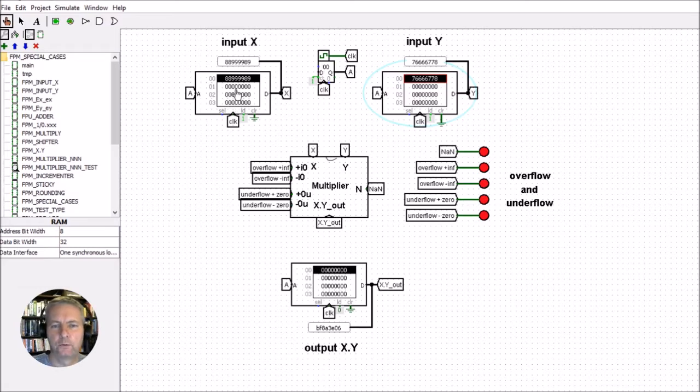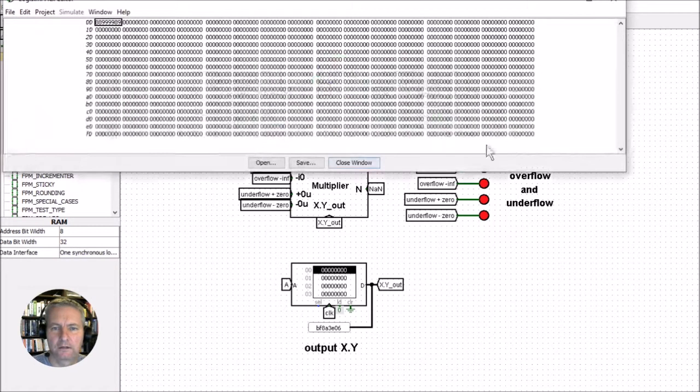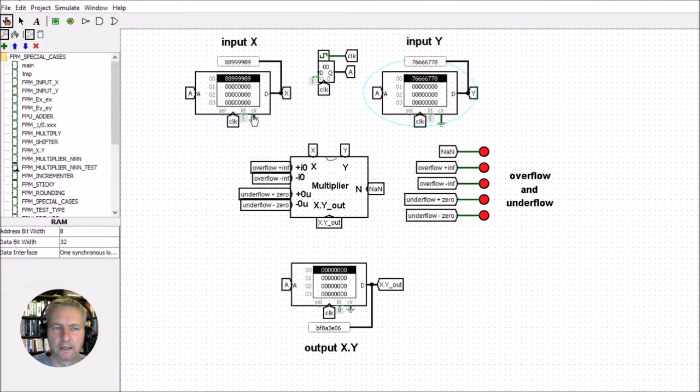Or as I will do over the next couple of days, I'm going to run a test script on it. But I have to get a test script together for it. So that means I can load the test script here directly. I'll create maybe 256 different values, and I'll stick it in just to check and see that it's working correctly. This is a little counter here just to count in the address for these RAM elements. And you get the final output here.